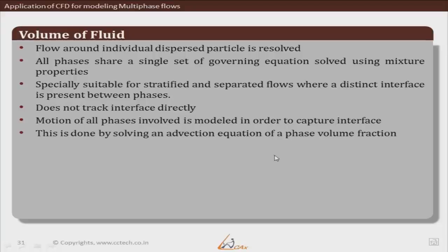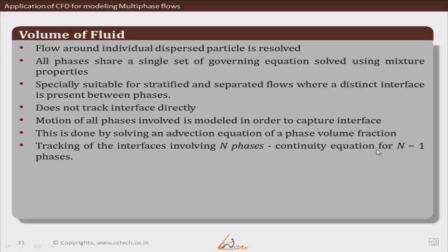In order to capture the interface, we solve an advection equation for volume fraction, and hence what we do is basically solve a continuity or advection type of equation for n-1 phases and find out the amount of phase involved in each particular cell or each particular location.